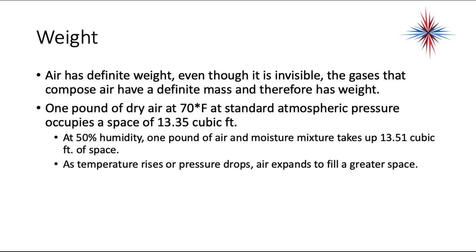Air has a definite weight, even though it is invisible. The gases that compose air have a definite mass and therefore have a weight. One pound of dry air at 70 degrees Fahrenheit at standard atmospheric pressure occupies a space of 13.35 cubic feet. That's an important thing to remember. At 50% humidity, one pound of air and moisture mixture takes up 13.51 cubic feet of space.